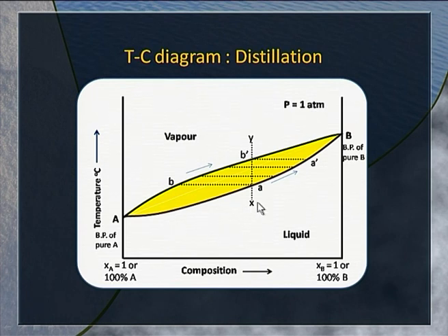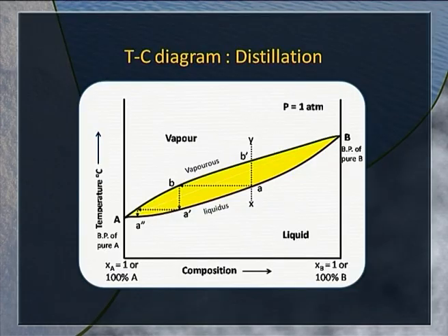So, in this case, we have brought about conversion of liquid into vapor, but distillation amounts to a slightly different thing, where we want to, say, separate A and B, and for that we can see how it can be done. Now, look at the same liquid mixture starting with composition X. You heat it. When you reach the point A, you can see that the vapors emerge out.